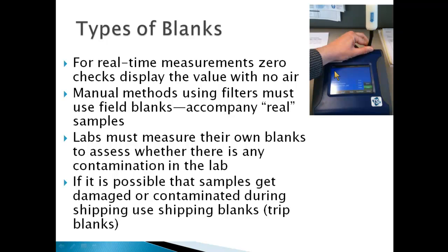But this is basically taking a blank, putting it up to the DustTrak inlet, and then measuring what sort of particulate matter is coming through, and it should be 0, right? So this is a sort of a blank that's used for continuous instruments.